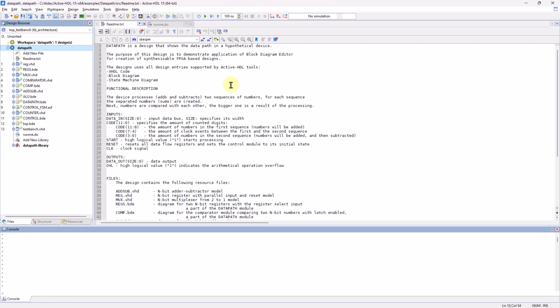What this tool does is that it shows how the CPU is utilized when simulating a design. It does this by counting the number of CPU ticks that each HDL statement, design unit, or instance of a design unit uses during simulation. This tool helps identify areas in a design where it puts the greatest amount of strain on the simulator. And this information can then be used to optimize the performance of your simulation environment, potentially making the simulation process more efficient.